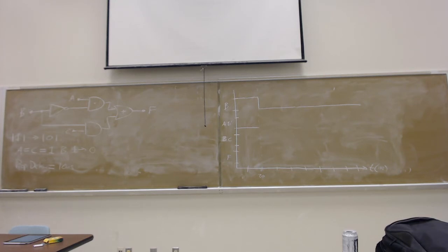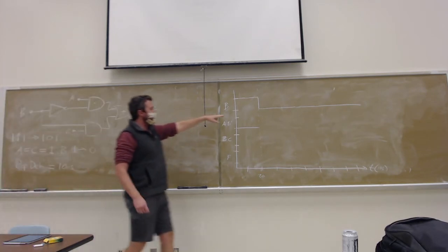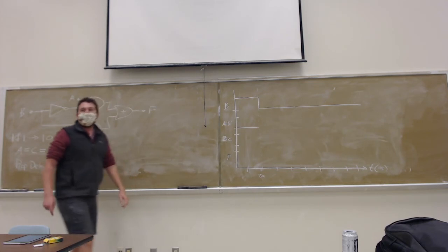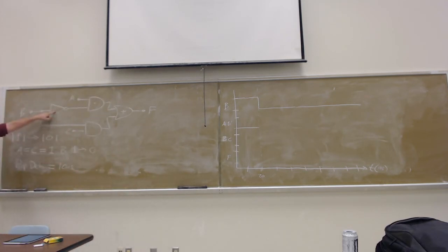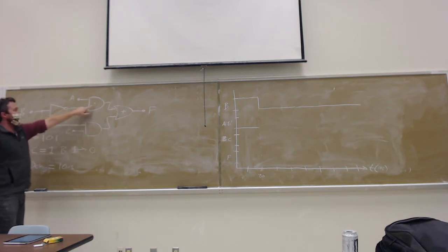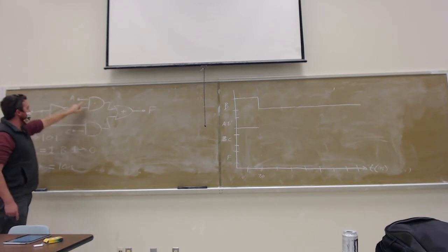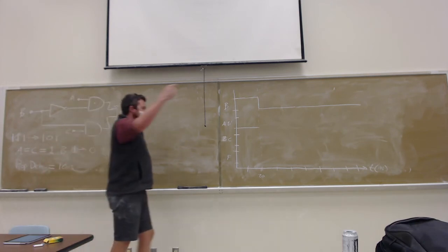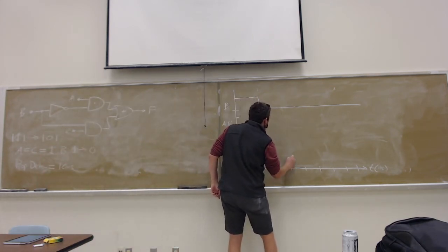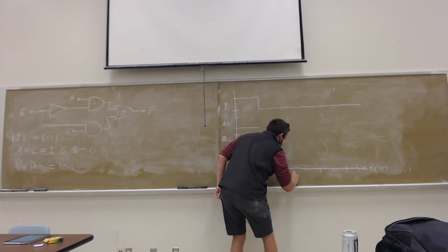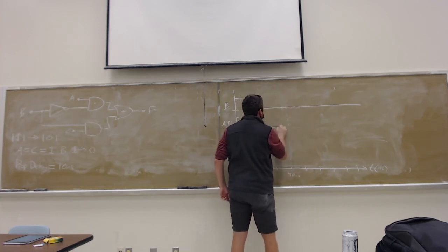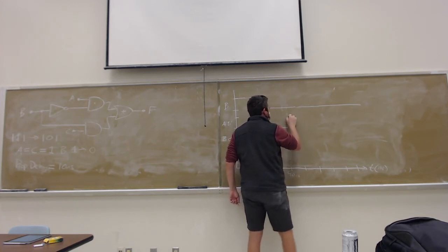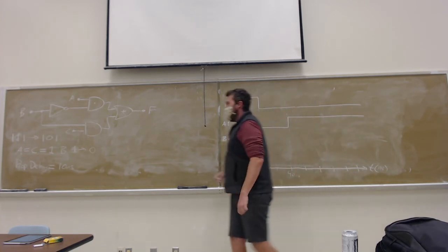After 10 nanoseconds. After the 20. So it's going to start at 30. Well, not at 30, because the transition here starts at 20, right? But remember, we got two gates here. The inverter. We get 10 nanoseconds for the inverter, and then the output of the AND gate is another 10 nanoseconds, which means for this gate its transition won't occur until another 20 nanoseconds down the line. So it's not until 40 nanoseconds that it switches from 0 to 1, but of course it's going to stay at 1 forever.